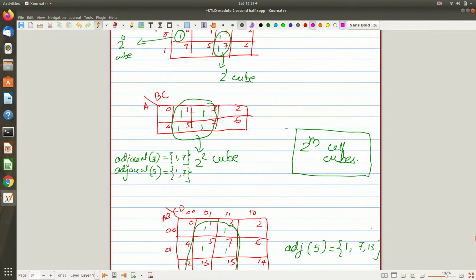So similarly here also, when you are grouping 2 cubes, how many variables are eliminated? 2 literals or variables. When I am writing the term literal, it is a variable or its negation. So that is a generalized term. Here totally there are 3 variables, so only 3 minus 2 literals remain in the final simplified expression. If there are 4 variables, then accordingly.